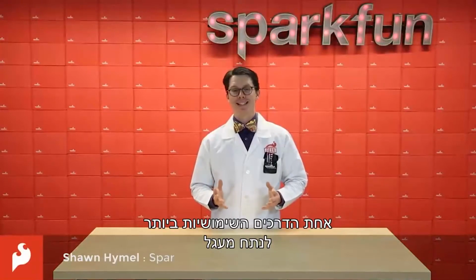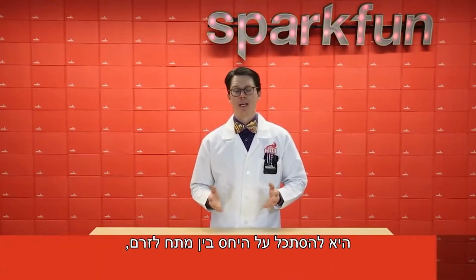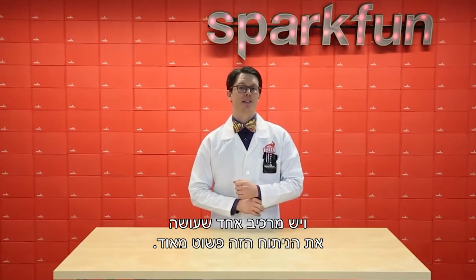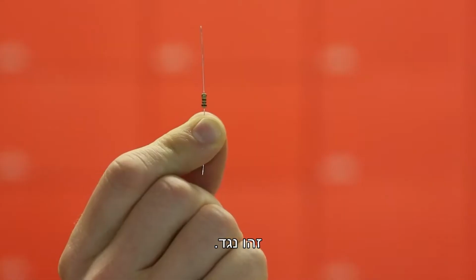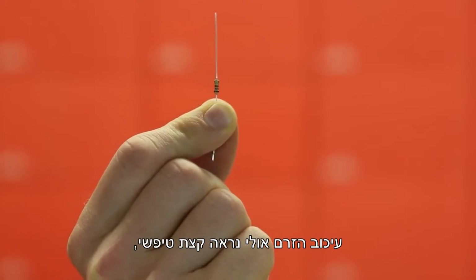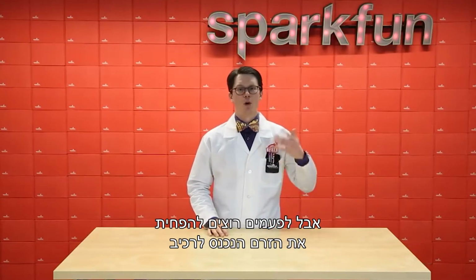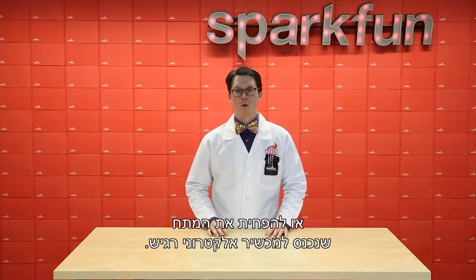One of the most useful ways to analyze a circuit is to look at the relationship between voltage and current. And there is one component that makes that analysis very simple. This is the resistor. Its function is very simple. It restricts the flow of electrons. Now, impeding current may seem a little silly, but there are times you may want to reduce the current flowing to a component or lower the voltage going to some sensitive electronics.